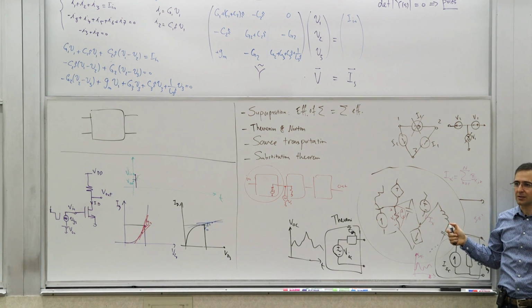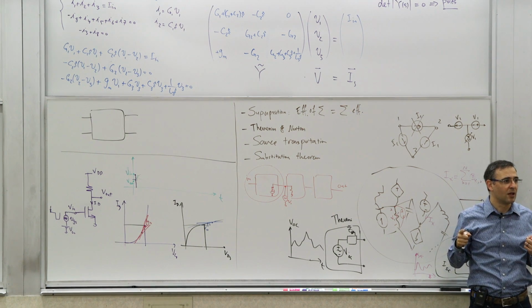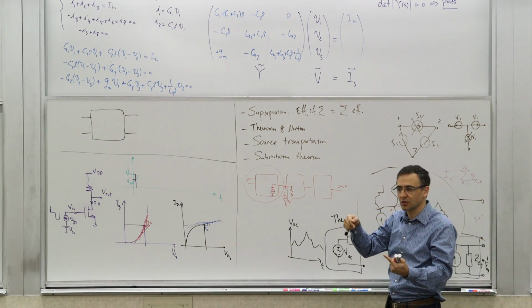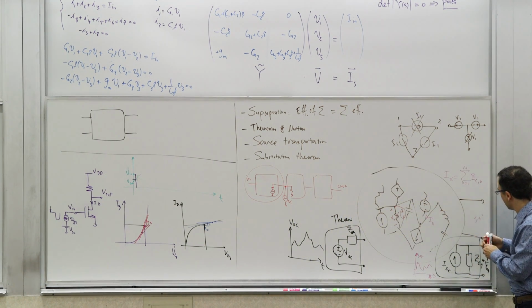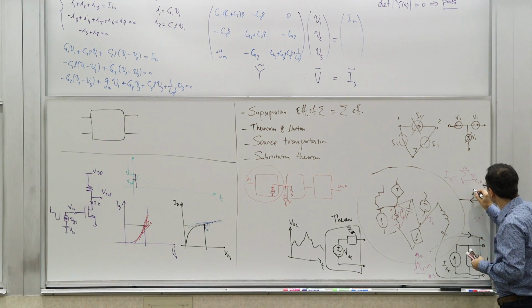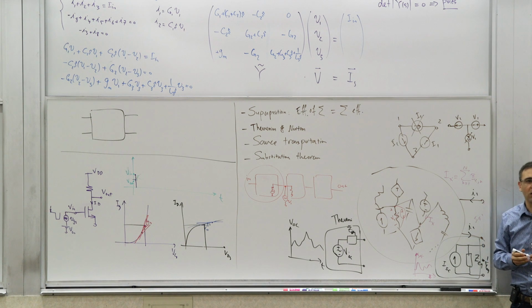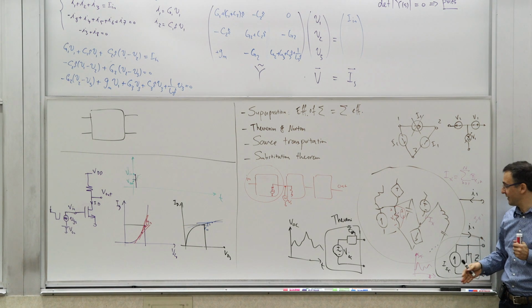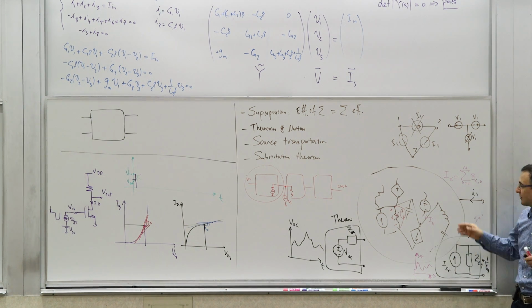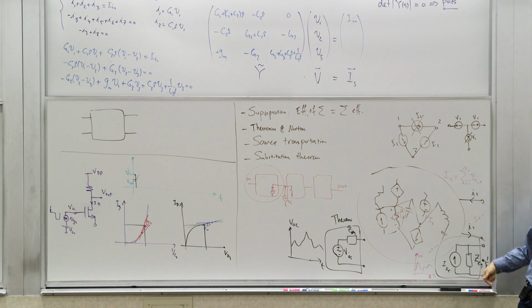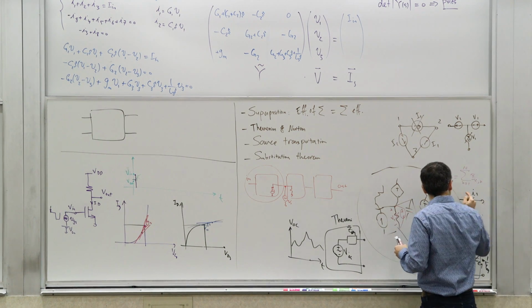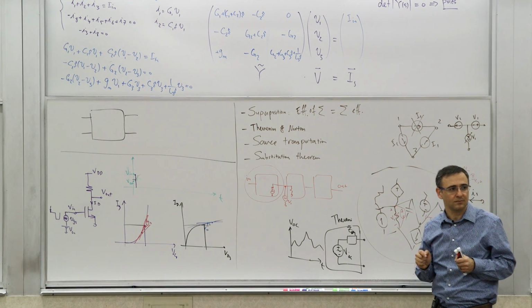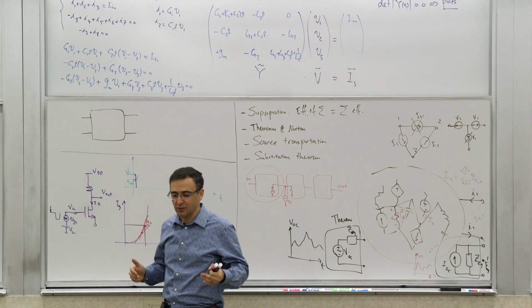You may say, what about a capacitor? A capacitor doesn't accumulate net charge, right? You have positive on one side and an equivalent amount of negative charge on the other side. So if that's the case, then this current is identically the same as this current at all times, if this is a circuit. And of course, if this is comparable to the wavelength, this doesn't have to be true. You can have a transmission line, where the current goes in, and it sometimes takes some time for it to come back out. But if the dimensions are much smaller than the wavelength, these two are always the same. That's another way of saying the speed of light or propagation speed is infinity.